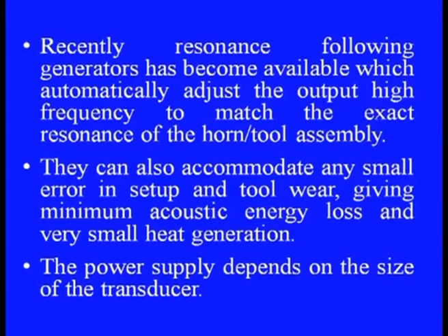Recently, resonance following generators have become available, which automatically adjust the output high frequency to match the exact resonance of the horn or the tool assembly. This is an advancement, in which this matching of the frequency is very, very important, and it is being automatically adjusted nowadays. They can also accommodate any small error in setup and tool wear, giving minimum acoustic energy loss and very small heat generation. These two are major factors. The acoustic energy loss will reduce the process efficiency, and the heat generation will also bring down the efficiency of the machine, or the productivity of the process will come down.